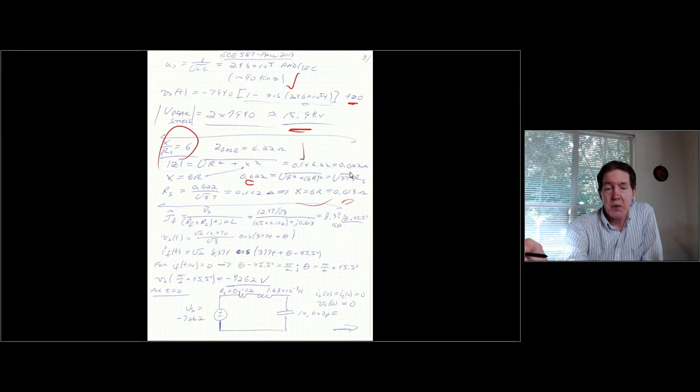And so now what we have for the fault current is a slightly different expression. Instead of just simply having the fault resistance, we're going to have a little bit of resistance associated with the source. We're going to get a little bit less fault current, and we're going to get a different phase shift. So again, I'm going to include my point on wave angle and the voltage, and calculate the fault current. I get a different angle.